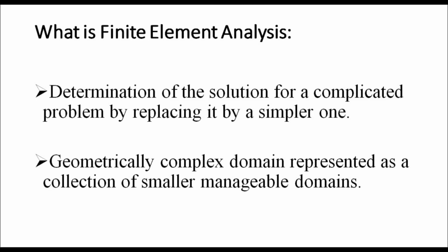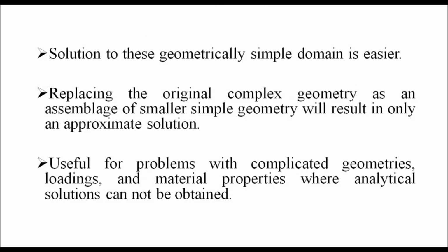This is the general concept about finite element analysis, what it says actually. A geometrically complex domain is represented as a collection of smaller manageable domains, and the solution to these geometrically simple domains is easier. Replacing the original complex geometry as an assemblage of smaller simple geometry will result in only an approximate solution, useful for problems with complicated geometries, loadings, and material properties where analytical solutions cannot be obtained. So, only in these areas, FEA is most useful.